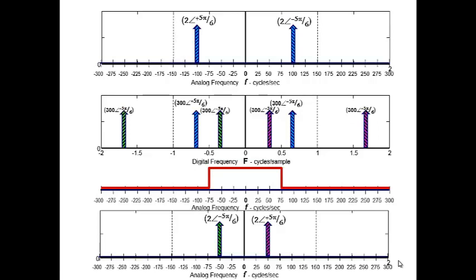So what is this signal? Let's go backwards. If I gave you this spectrum, what signal is that? Two impulses at the same frequency with this phase. We would call that a cosine. We call that x alias of t. Two impulses with weights of 2 give me a 4 cosine 2 pi.